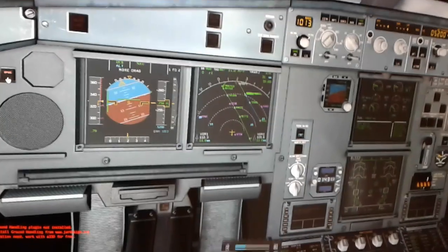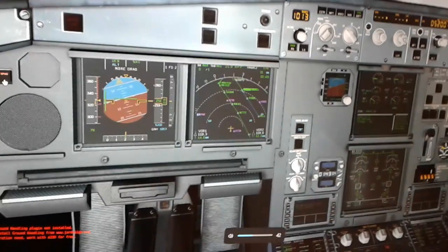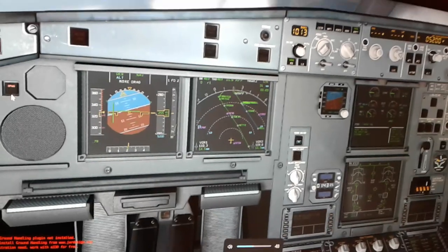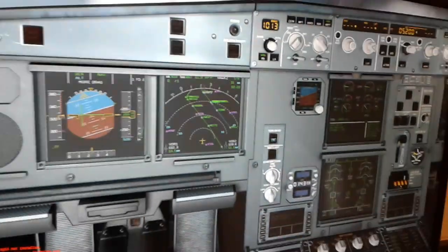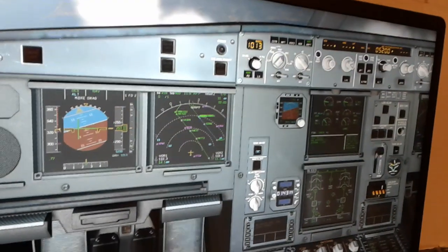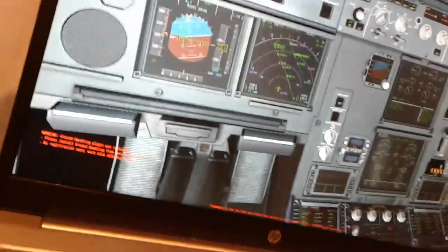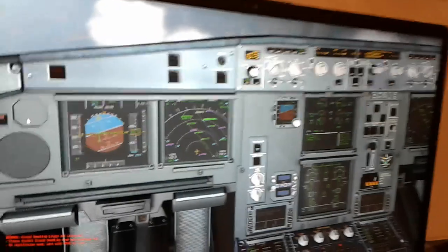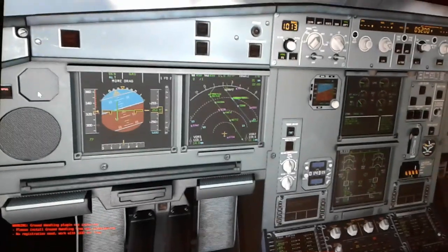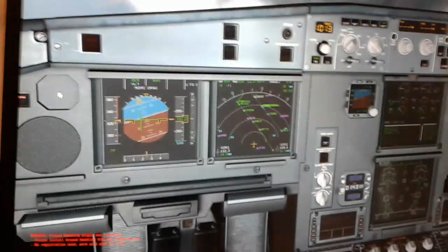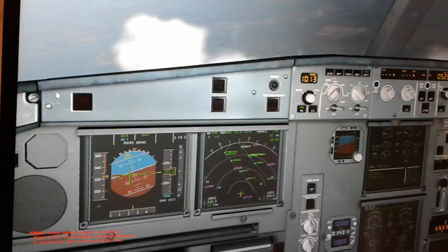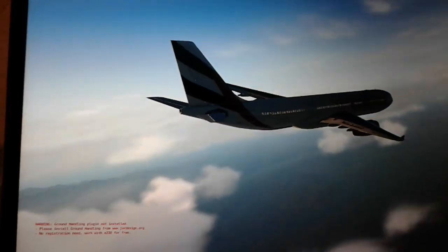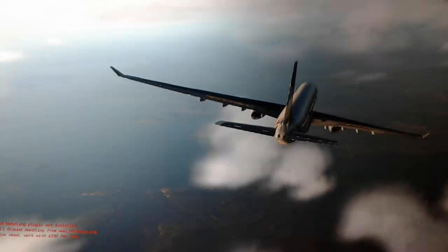Power was not letting the aircraft descend. We're gonna disarm the auto thrust and lower the thrust levers below that takeoff go-around position. This is how the Airbus philosophy works. Airbus A330 and A320, almost all Airbus aircraft are pretty much the same.